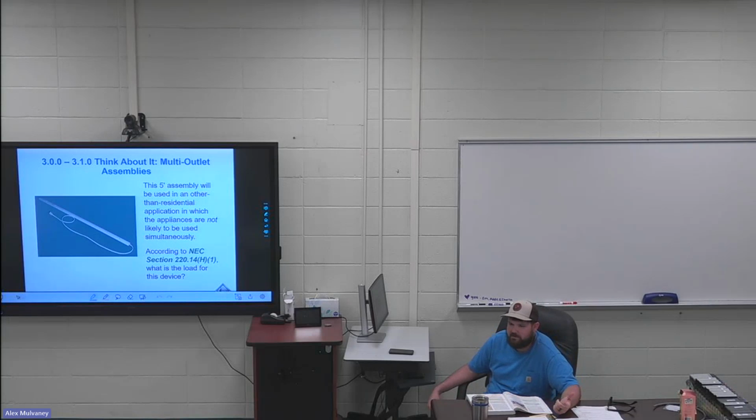All that means is, if I have a sign on a 20 amp breaker, it can't take up more than 16 amps because it's a what? Continuous duty, right? So down here it says to determine the volt-amp load for a circuit, multiply the amperage by the voltage: 20 amps on 120 volts, 2,400 volt-amps. Then you figure 80% of that; 80% of 2,400 is 1,920.